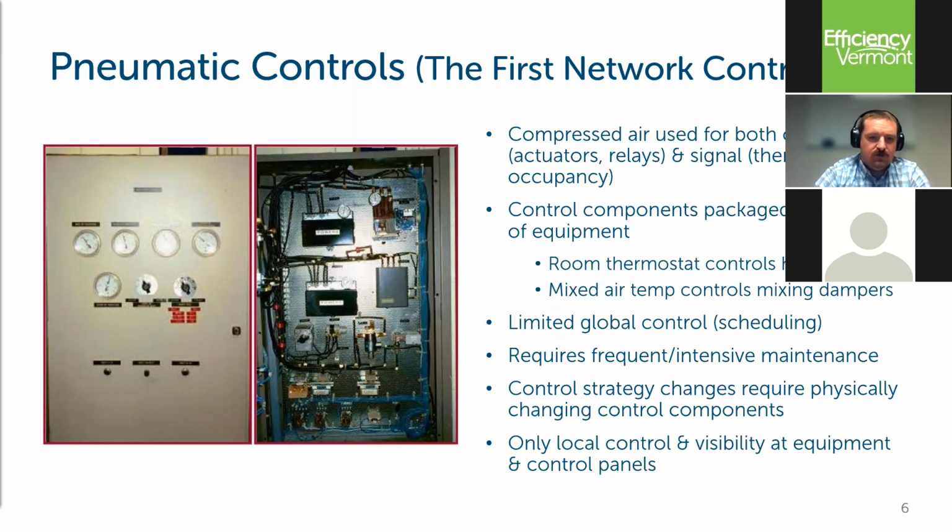These pneumatic controllers were typically packaged for specific purposes. So we would have a room thermostat controller that would control a valve or a fan. We could have a mixed air damper pneumatic controller that would have a mixed air temp sensor that would drive the outside and return air dampers. So these were very component based.